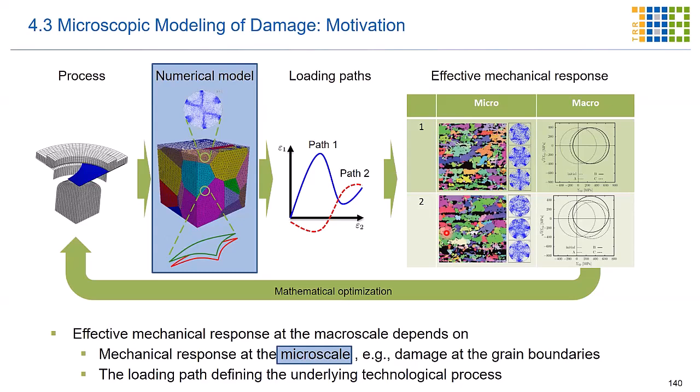And for such microscopic damage models, it's quite often almost impossible, or practically impossible, to perform a simulation of the entire body. So you find very often calculations or examples where you have a so-called representative volume element, an RVE, where you know stresses or strains that are applied to different points of your formed part, and then you use these loading paths and only compute them for the material point or for this representative volume element.